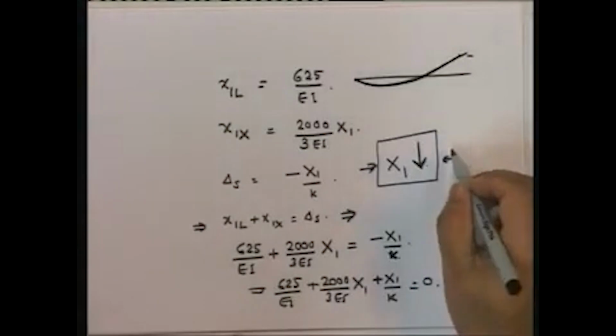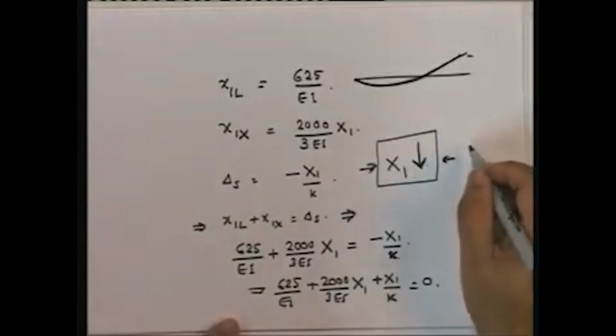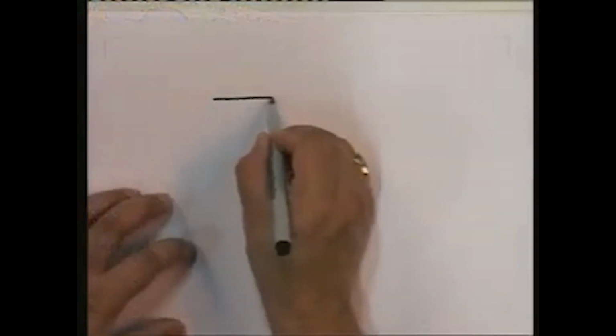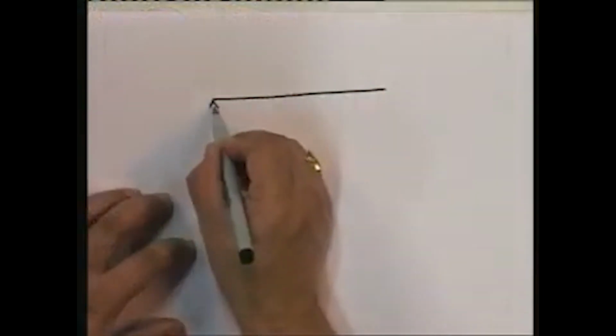Note that in this particular case, as opposed to the truss, the foundation flexibility directly has an effect on the internal forces in the member. The bending moment diagram will change because the support reaction has changed. Now let us look at the situation of foundation settlement. How does foundation settlement have an effect? Let's take the same case.